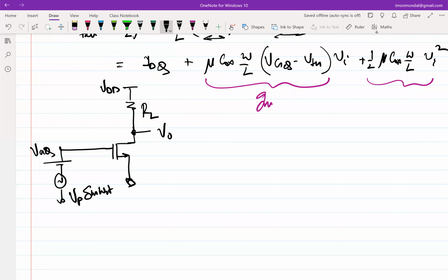Okay, so one answer was VGQ plus small signal. In this case, Vp is going down, so VGQ minus Vp should be greater than or equal to threshold voltage. Okay, so why do you say this? I presume it's because the transistor is completely cut off. Now, while this is mathematically true, there is a caveat if we use this constraint.